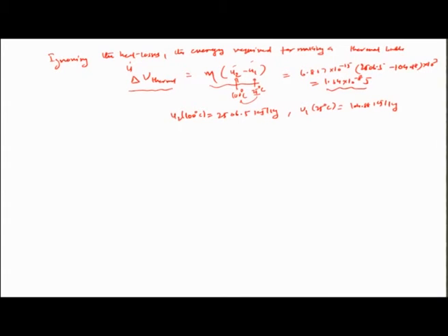So, in both cases obviously an expansion work has been done because even if it is a boiling phenomenon and generation of a vapor state, the bubble has to nucleate at some point and slowly expand to come to that 28 micron size. In a similar manner, in electrolysis as well, it has to nucleate at some center around the electrode, probably where the electrons are being pumped in, and grow in size eventually against the delta P pressure. So, some amount of work is needed to overcome that pressure and maintain the two phase condition so that the bubble can expand in size.